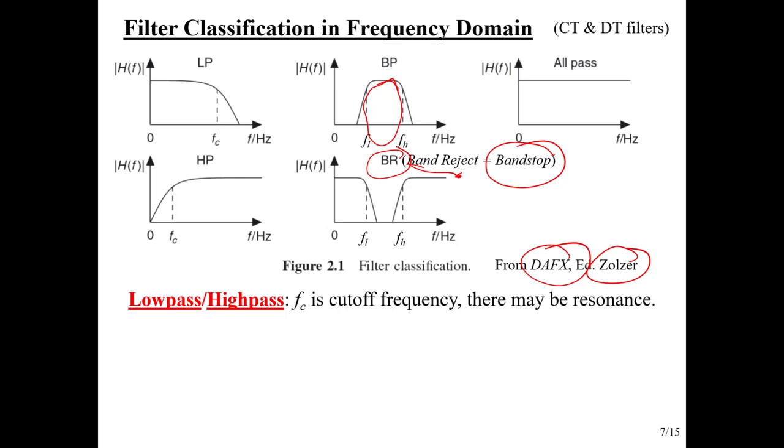You've got band pass and band stop. So again, you've got 2 characteristic edge frequencies, except now we're stopping the components between those edges and passing the components outside that band. So those can sometimes be useful in audio. Maybe there is some region of frequency that is not particularly nice for what you're trying to do, and you want to notch it out. So that's another name for these, especially when this width is very, very narrow. We might call that a notch filter.